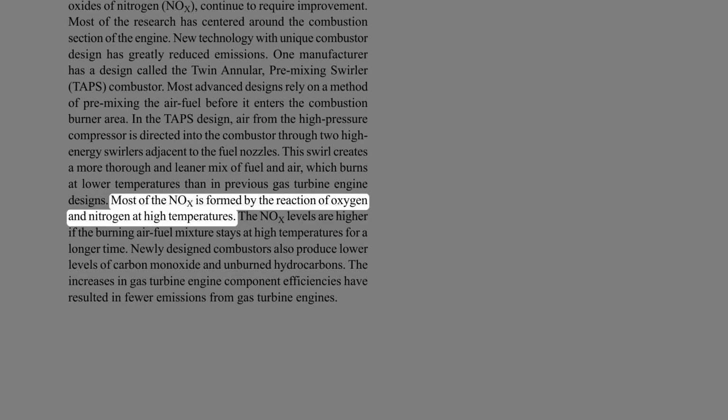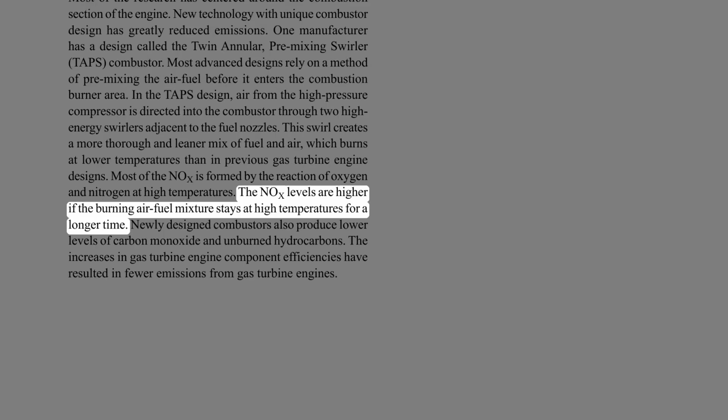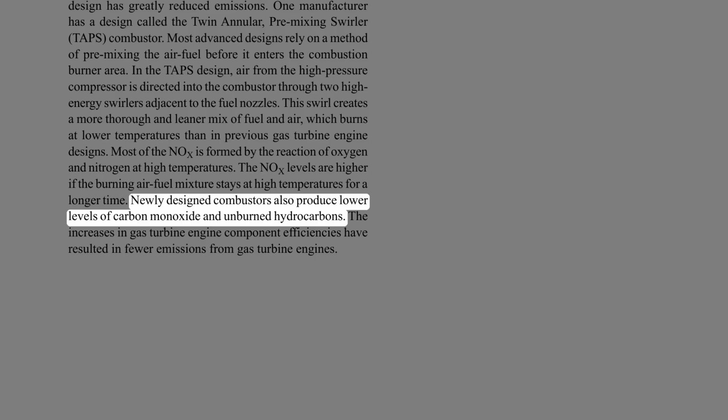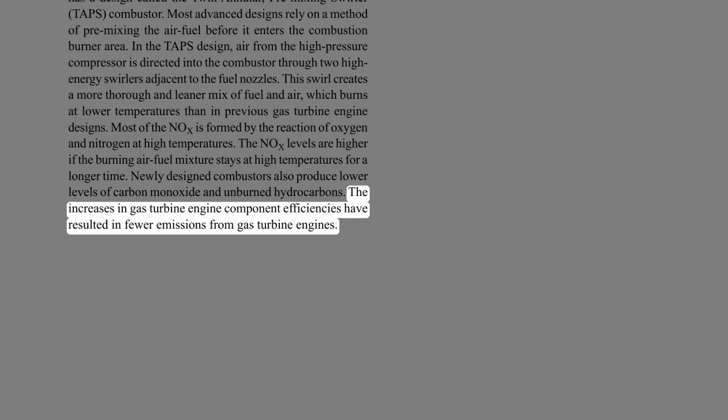Most of the NOx is formed by the reaction of oxygen and nitrogen at high temperatures. The NOx levels are higher if the burning air-fuel mixture stays at high temperatures for a longer time. Newly designed combustors also produce lower levels of carbon monoxide and unburned hydrocarbons. The increases in gas turbine engine component efficiencies have resulted in fewer emissions from gas turbine engines.